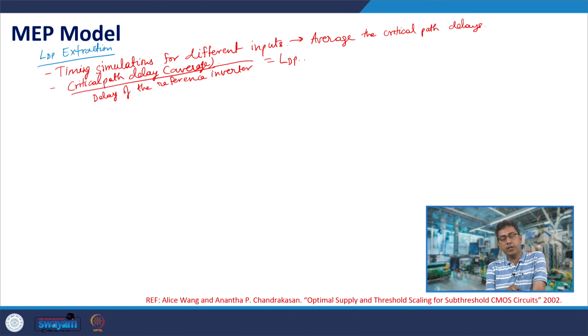What is the implication of a change in threshold voltage? When you increase the threshold voltage, you would reduce the leakage current, but the time period would increase.